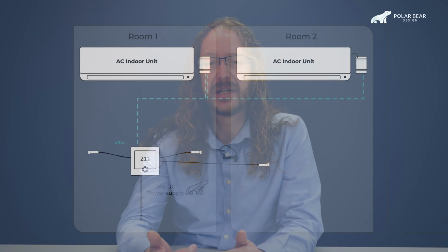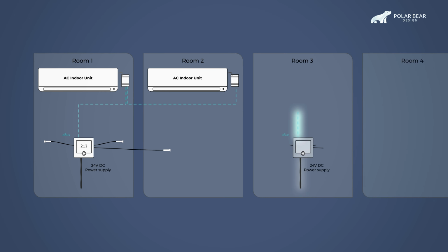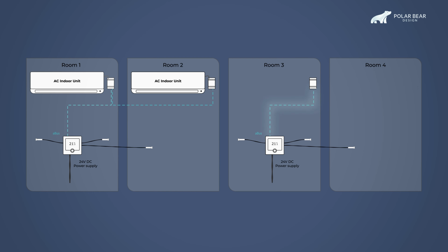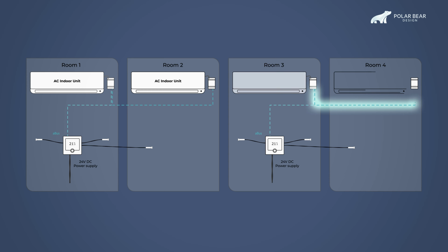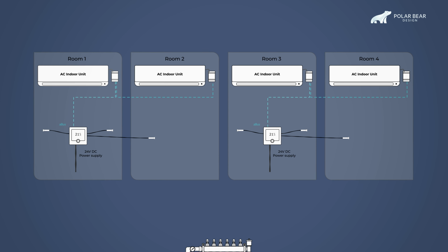This gives the thermostat a room temperature reading that is much more representative of the temperature experienced by the people in the room. This blending can include the return air temperature reading from the AC unit, so the occupants can still benefit from this, even without adding additional sensors, just by using the built-in sensor and the AC unit's return air temperature. Considering each room, or each pair of rooms in this way, is a great approach even when designing a larger system. It's then straightforward to expand the design to incorporate other climate features such as underfloor heating.